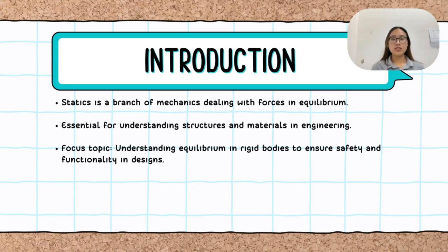A rigid body is in equilibrium when all the forces and torques acting on it add up to zero. This means the object doesn't move or rotate. To analyze such a system, we create a simple model of the object, draw a diagram showing all the forces acting on it, and then use equations to find any unknown force or moment. A common example is a ladder leaning against a wall, which forms a triangle with the ground and wall.